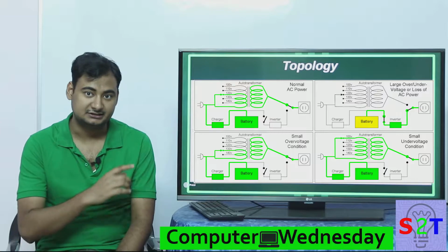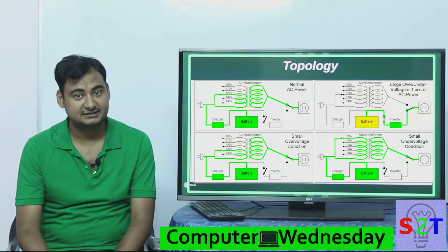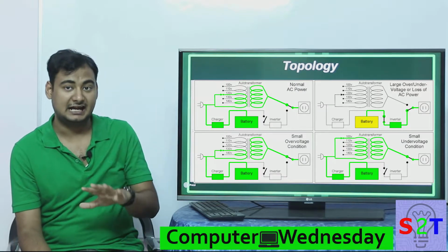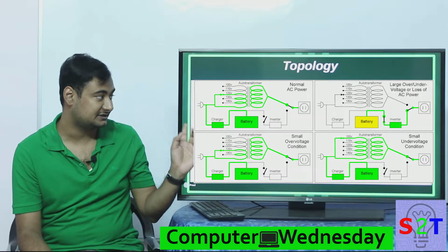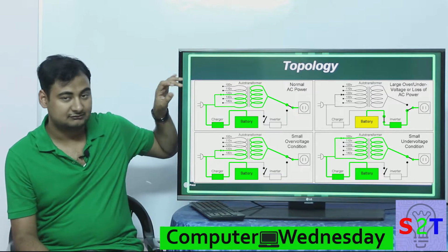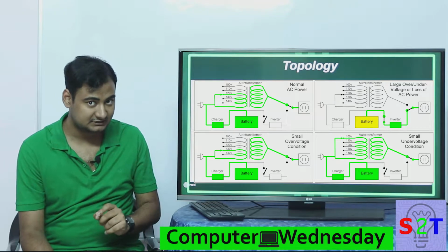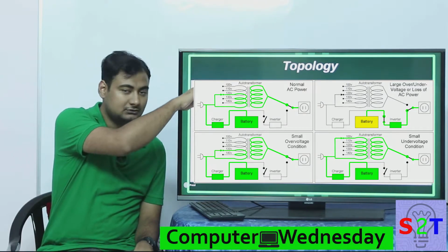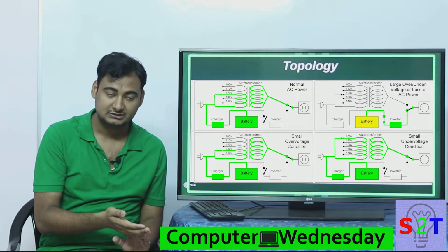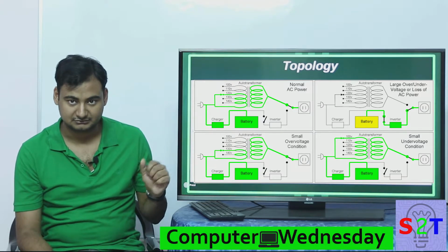So when you turn it on, the power that is coming in from the grid goes to an auto transformer. This is their first line of defense. As you can see, it can handle a little bit of voltage fluctuations. This is a circuitry for a 110 volt or 120 volt system. So if low voltage comes in from your grid, it will switch to UPS first. During that time, it will make the auto transformer step up the voltage, and then it will disconnect the battery, and then again you will have the power directly coming from the grid.